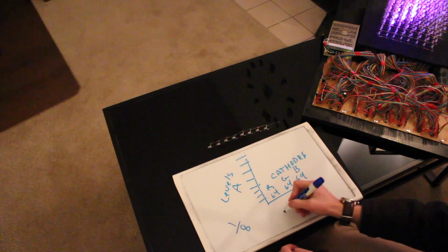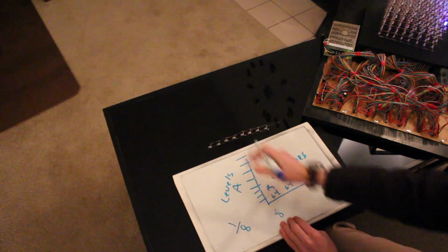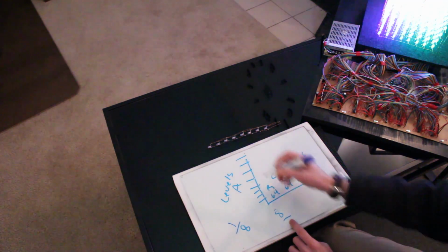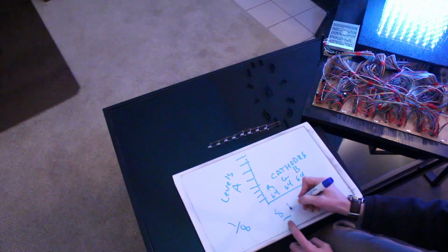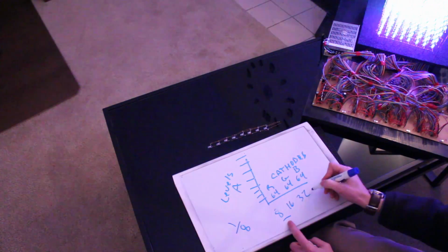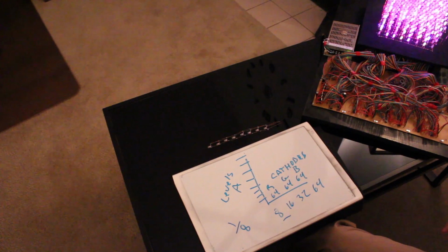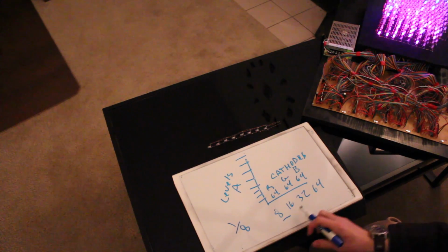If I wanted to write a 1 to one of the LEDs, it would have to be within the 1 to 8 counter. So it goes 8, and then 16, 32, 64. And I'm not using 8-bit modulation. I'm actually using 4-bit modulation.